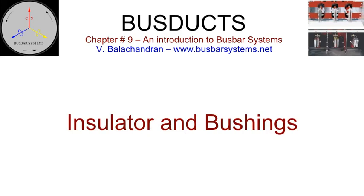Insulators and bushings. The industry has standardized on the type and material of insulators and bushings for the support of conductors in low voltage and medium voltage bus ducts. Dough-molded compound, sheet-molded compound, or glass-reinforced epoxy or polyester resin sheets and pultrusions are used for low-voltage bus duct. Mechanical strength is the most important criteria. Cast epoxy resin and porcelain insulators and bushings are used in medium-voltage bus ducts. The dielectric properties are the primary criteria. Insulator fixing in enclosure and conductor mounting or clamping on insulators varies depending upon the designs adopted by manufacturers.